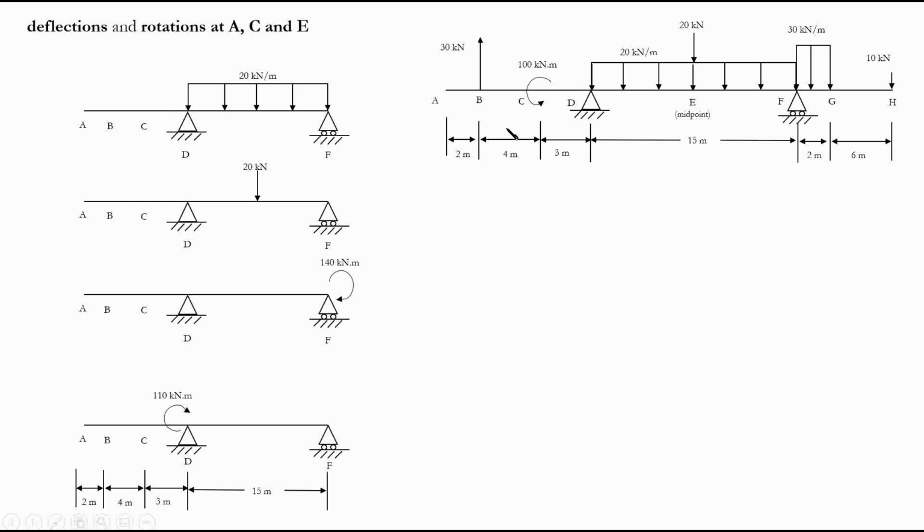before proceeding to the cantilever portion, one question you might ask is, why are we drawing this portion? Aren't we only finding the simply supported portion? The answer is, you're correct, but we're drawing this portion to find the rotation and see how the beam deflects.